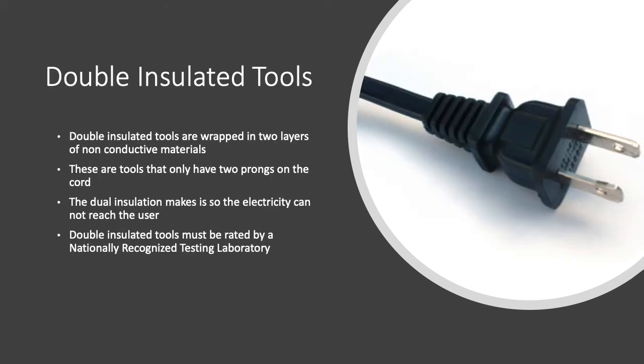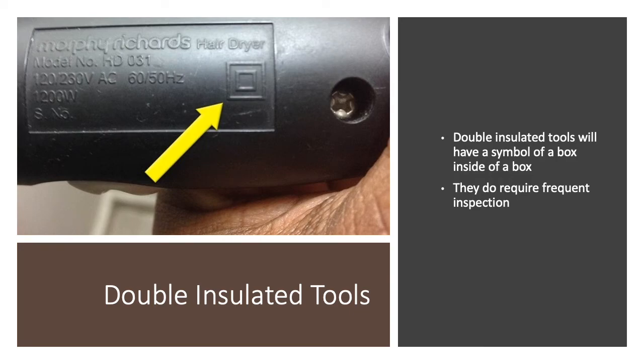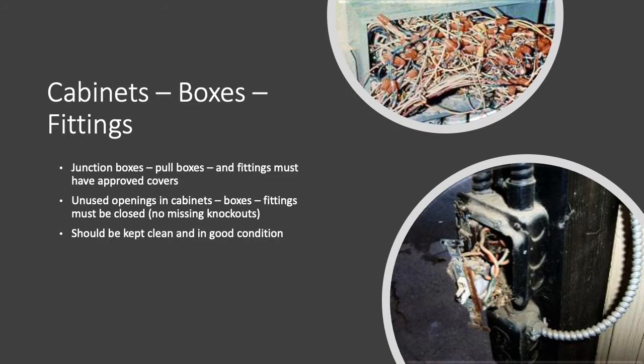So we talk about this in hand and power tools, but just to reiterate, there are double insulated tools, which essentially came about because back in the day they made tools out of metal because they were heavier, more industrial, and they lasted longer. The problem with that was that if there were any loose connections or wires inside of that tool, they made contact with the housing of the tool, shocking and sometimes electrocuting.